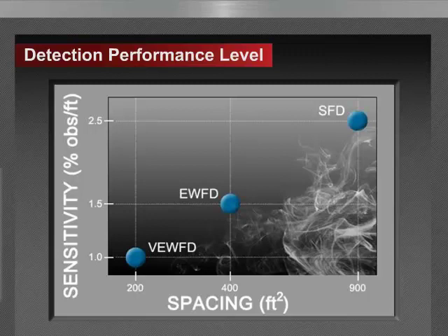So the answer would be no, we're not derating. If we're doing very early warning fire detection, the air velocities are in excess of 60 air changes, we're still going to be at 200 square foot as defined in NFPA 76 for very early warning fire detection systems.